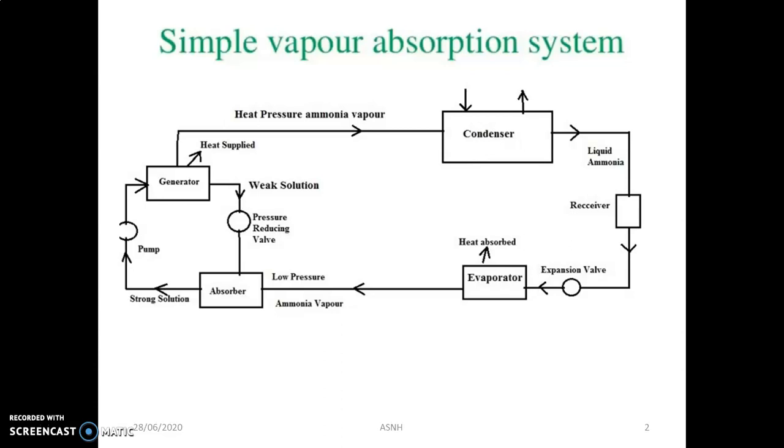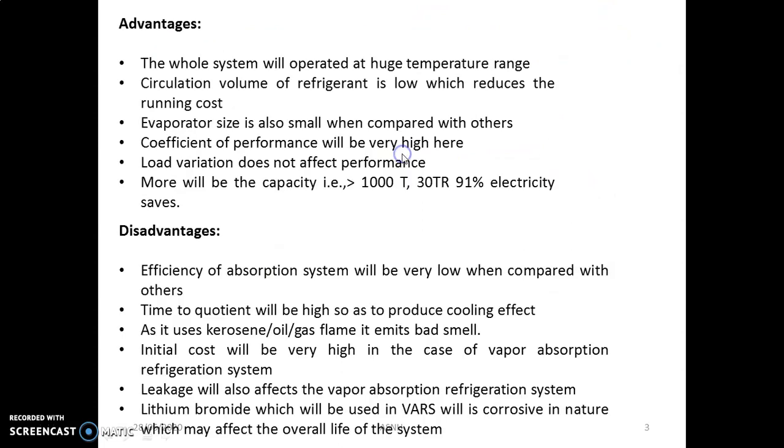Always keep in mind that in the vapor absorption refrigeration system, ammonia acts as the refrigerant and aqua, that is water, acts as the absorber, and the compressor is replaced by the generator, absorber and pump assembly in the case of the vapor absorption refrigeration system.